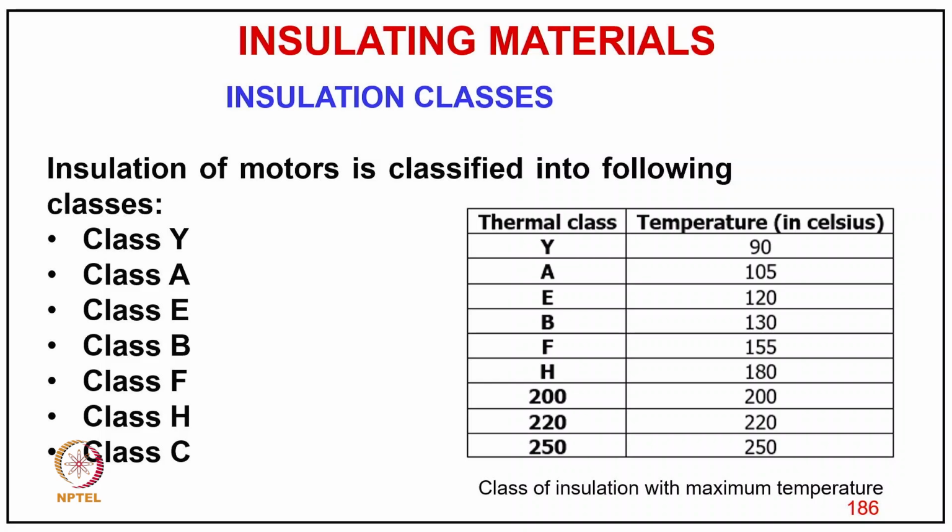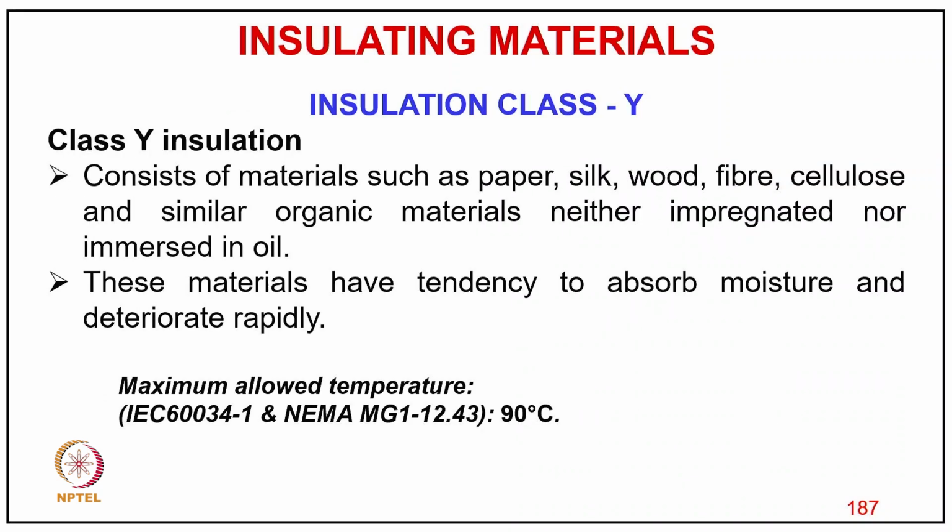If you take a better class of insulation compared to class B, then we can allow a higher temperature rise. It means the same surface area can dissipate more of the losses in the machine, so the machine size can be reduced. This becomes very important in the design. Insulation uses only a very small volume of the machine on the conductor, but it really decides the cost and size of the machine, since you can allow the dissipation of more heat, produce more losses, and get more output from the same machine.